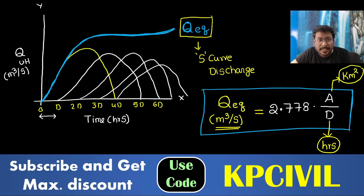The reason behind that, why? The factor is already multiplied for unit conversion. The factor 2.778 is already given, so you need not multiply with any factor or perform any unit conversion. Units are already converted. Area in square kilometer, duration of rainfall in hours. 2.778 into A by D gives the equilibrium discharge or S curve discharge. Other than this, nothing is required for S curve. This formula is most important for your AE exam. You have a simple numerical question.